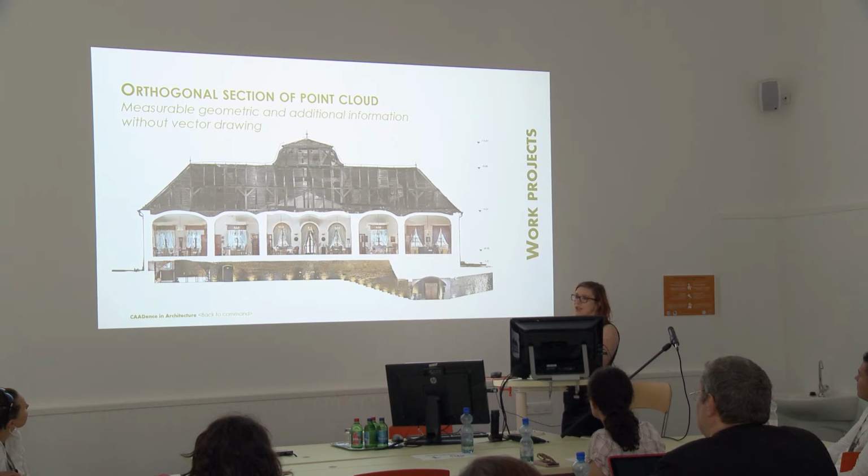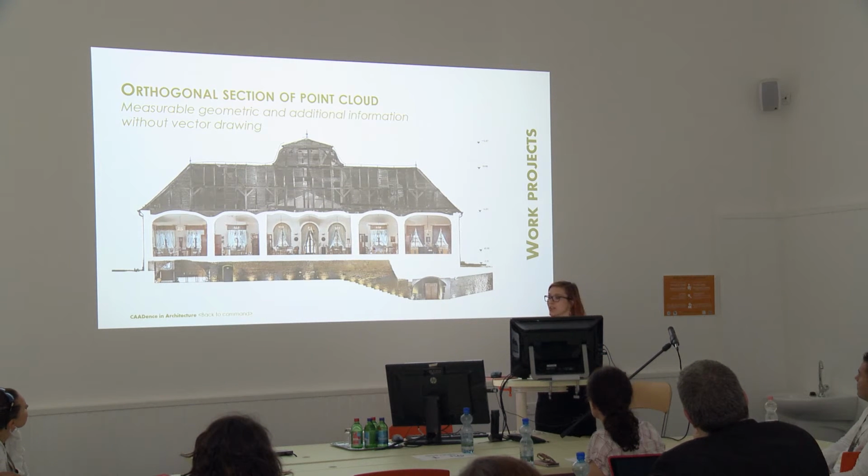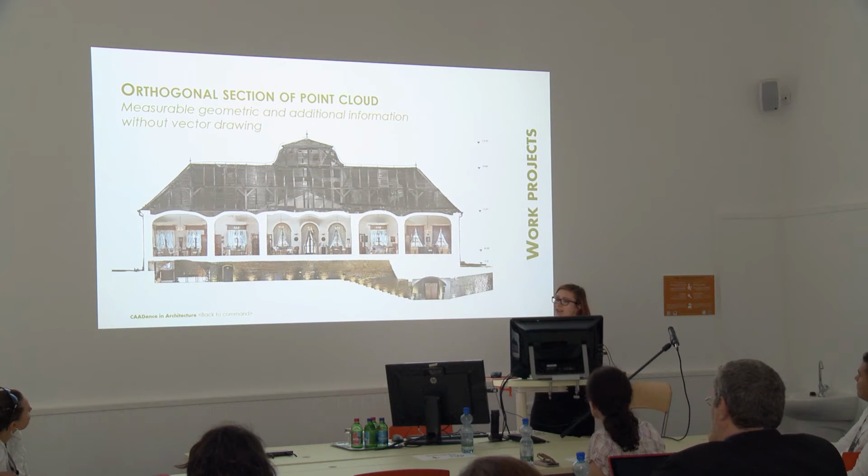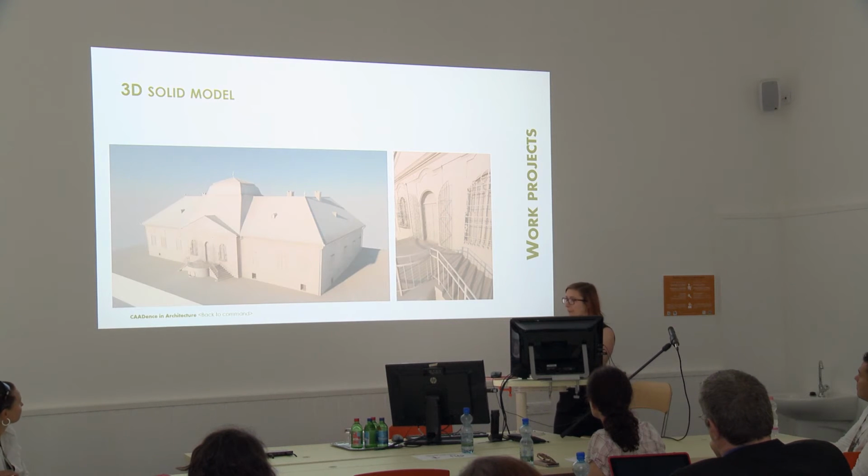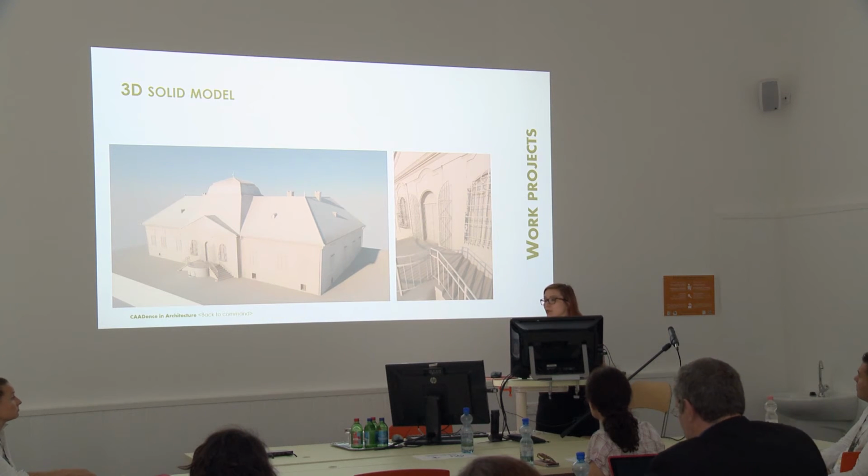After the data processing phase, orthogonal point cloud images and 3D architectural drawings were created. The section of the point cloud shows the real undistorted section of the building and gives measurable geometric and thematic information without the vector drawing. A 3D model was also created based on the point cloud. The model and the orthogonal images were made for architectural visualization and to demonstrate the possible utilization of the many abandoned